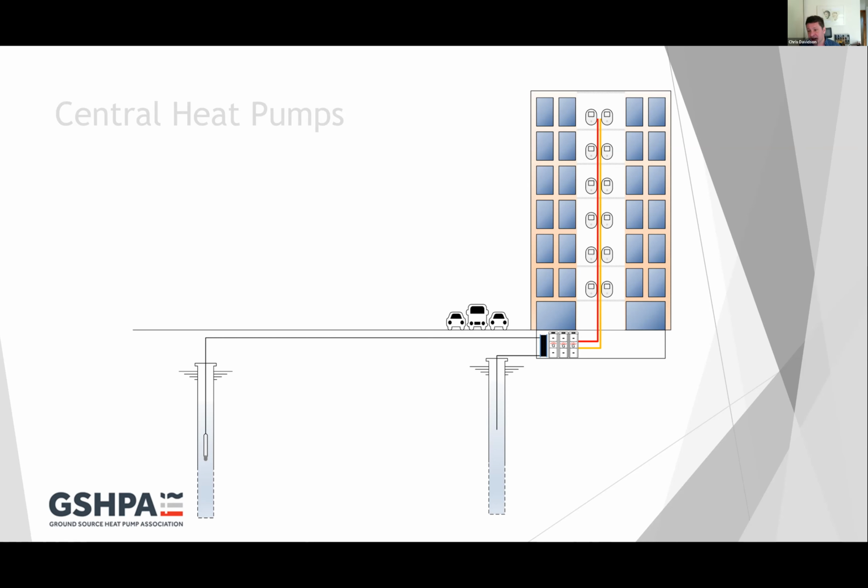The benefit of this system is that all the plant is centrally located, and you've got a more conventional district heat type approach. But you do have some other disadvantages as well. The cost of these heat interface units is not insignificant, for example. Also, this pipework has to be very well insulated to deliver that heat up the building. There's also quite commonly reported problems with the risers and the communal areas in which the risers tend to be located actually overheating in the summer, because this district network needs to be running all year round to deliver domestic hot water.